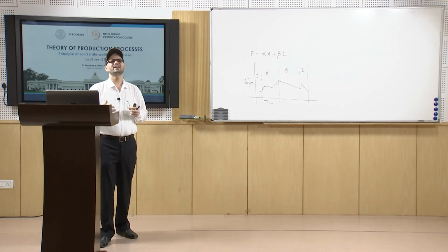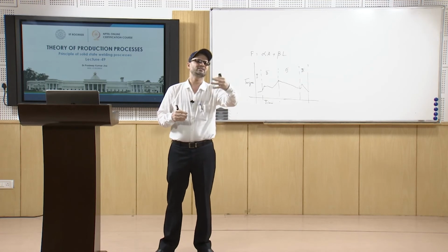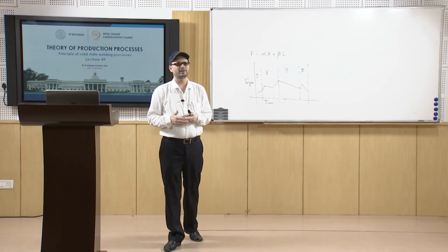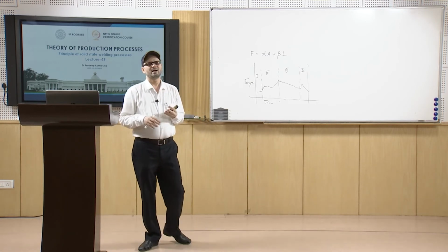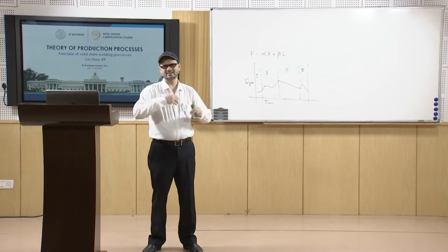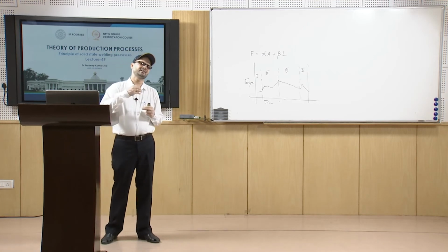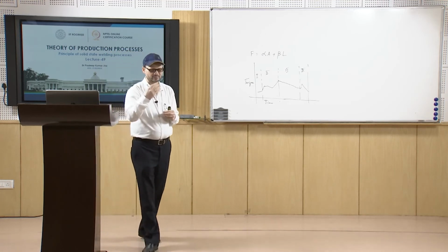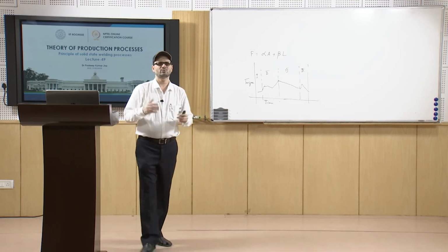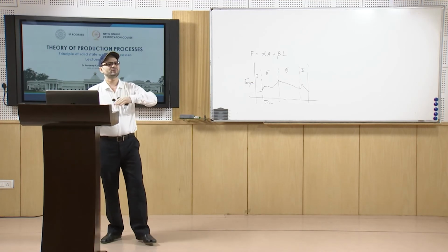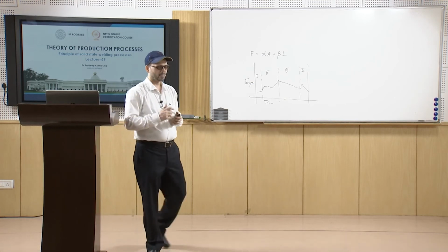Now there are different variants of friction welding, like inertia welding and friction stir welding. In inertia welding, the inertia is used by attaching a flywheel, and power is attached to that section. Since we are using the inertia of that flywheel, you will have a moment of inertia attached. Based on that, you will have I omega square, where I is the moment of inertia of the flywheel and omega is based upon the rotational speed.